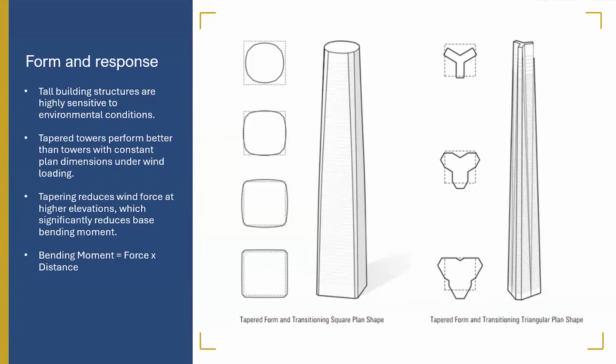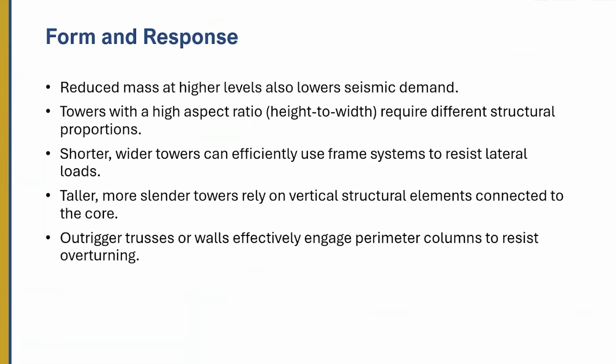And this is a tapered form, again, from this one to that one. Architects use this as a design concept. Start with it, and think of the building ultimately fitting in this somewhere here. That's why you see so many changing plans that fit this idea ultimately. So we reduce the mass at higher levels for lower seismic demand. We also reduce the area for the wind exposure. So it's very good both ways, because mass at the top for earthquake is not good. We will learn later, probably you already learned. And width at the top is not good for wind. So both of them require that we reduce the size of the building at the top.